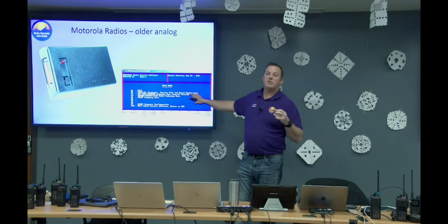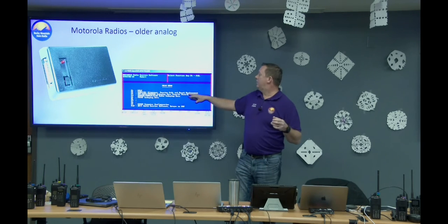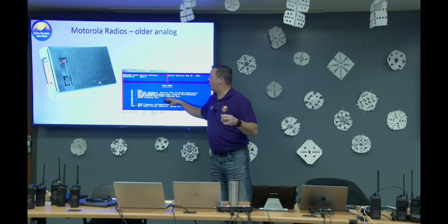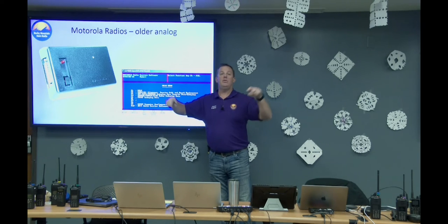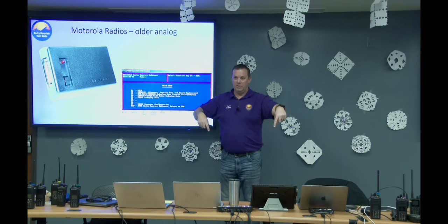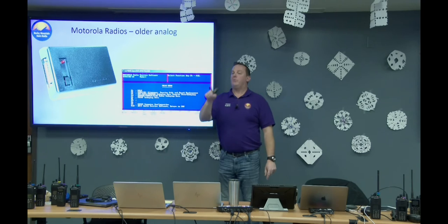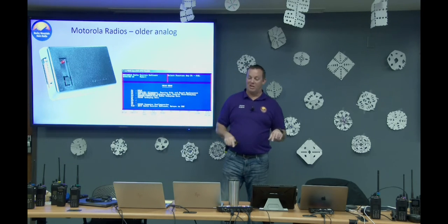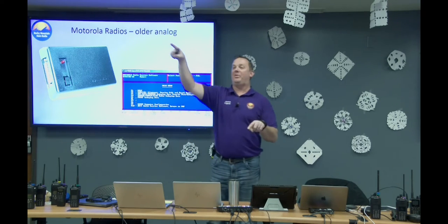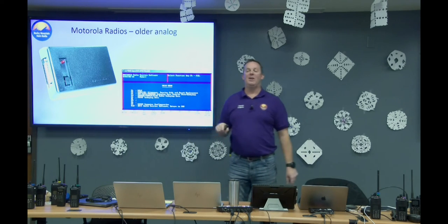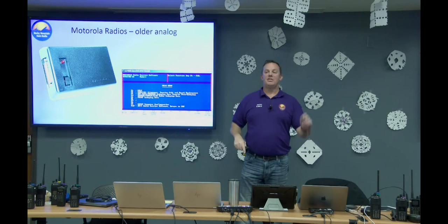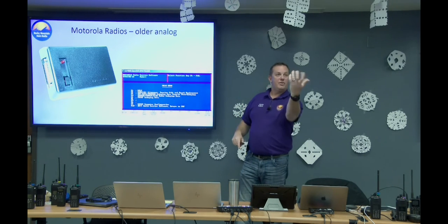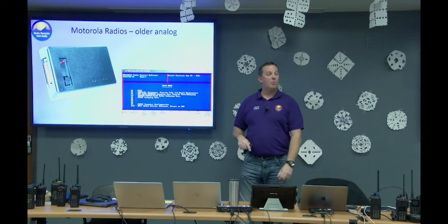And in RSS, the way you do that, you're in the change, create, code plug data, and you're changing the frequency, you hold the shift key down. Correct. Hold the shift key down for everything but the decimal point. On the screen, you're going to be typing pound, at, 3, all the symbols up there. And then when you hit enter, it's going to say this is out of band, and it's going to change to the frequency you wanted in the RSS, and it works.